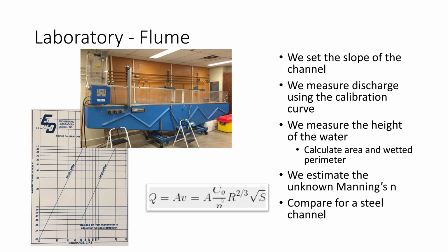And once you get your Manning's coefficient, you're going to compare it with tables to see how well your Manning's coefficient compares to that given in the literature. So that's the basic idea behind today's experiment.